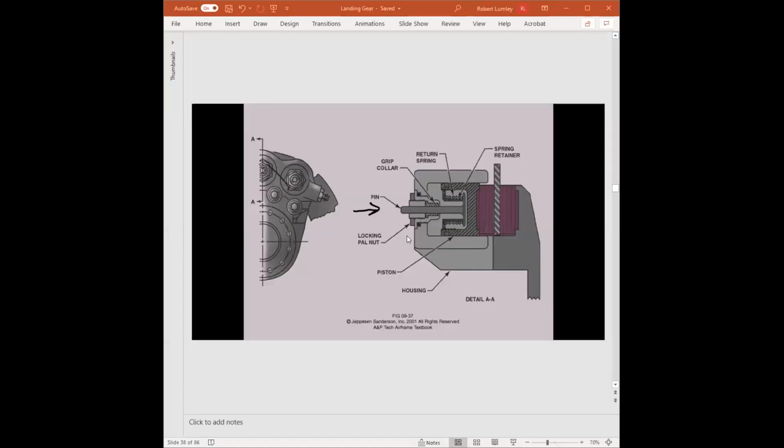Okay, so hopefully that's a better understanding of the automatic adjuster. Once again, the automatic adjuster is there to compensate for the wearing of the pads. The automatic adjuster, how far the pin sticks out from the caliper, can be used to indicate brake wear.